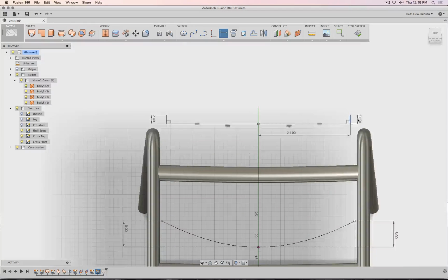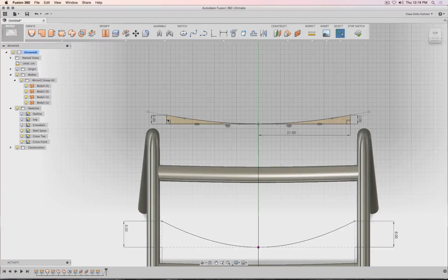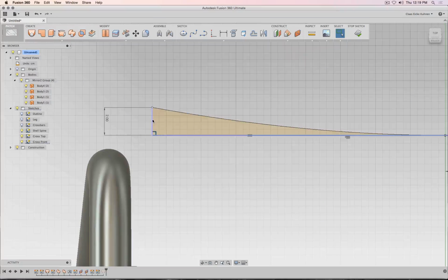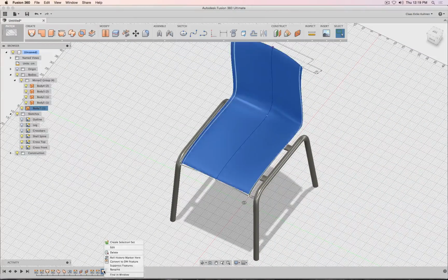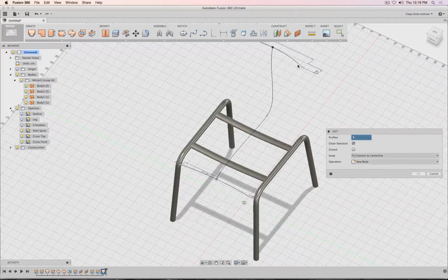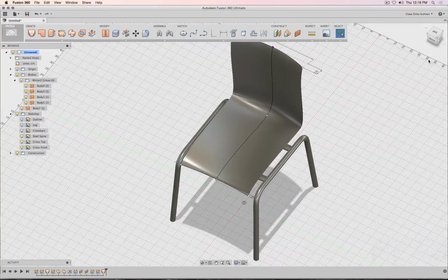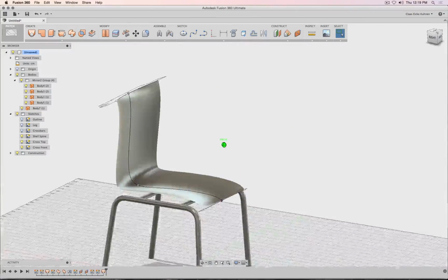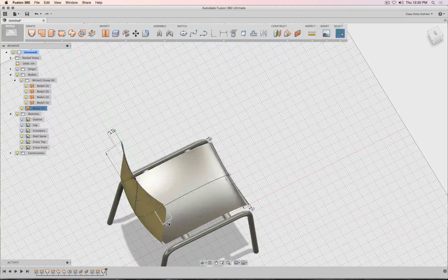So you see, all this dimensioning is quite some work to do, but it really pays off afterwards. And here, this line and this one, all normal. Okay, stop sketch. And we have to update this one because it's using the wrong parts of my sketches. Convert to center line. Okay, that's good. And maybe here now we give this a really minor arc, just a small bend. Maybe this one a little bit less drastic.